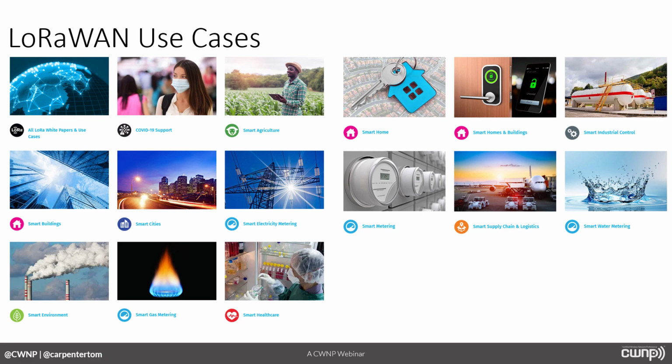Well, okay, in any one of these environments that are listed here, I think you can imagine some scenarios where you might have an IoT device that needs high data rate, something that needs maybe 50 to 100 to 200 kilobits per second or something. And you just can't get that with LoRa. So it's not the solution for that. But in all of these different industries or verticals, I'm sure you can also think of things that only need a few bits per second and they'll be okay.